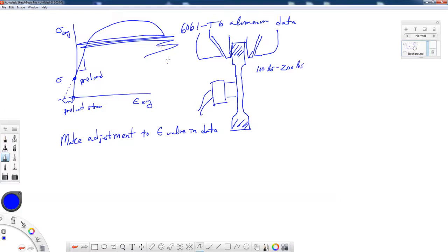This data right here for the strain channel after the extensometer removal isn't good. It's good for the load, but it's not good for the strain. Okay, so I'd like for you to go and edit your data to get rid of that extensometer removal point and anything after that on the strain side. Now, if you do need to find your final fracture stress, you can look at the final load before it breaks, and that's still a good value.